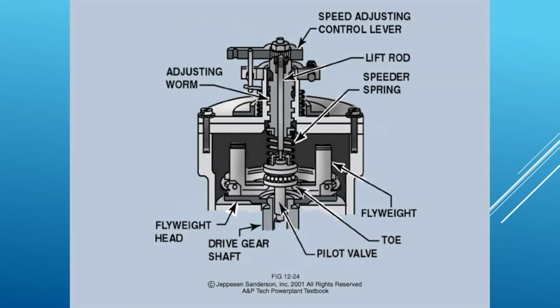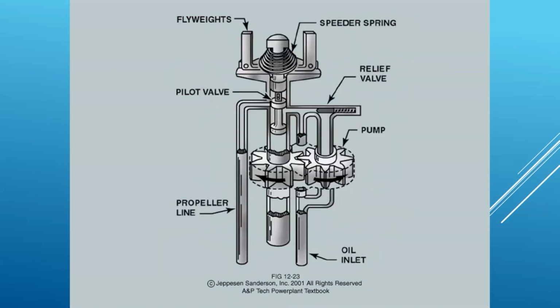To make it a little bit more complicated, we add a little bit on. So here's our same fly weights going to the pilot valve. Now, the opposite can be true as well, I should say. If this was lower, when the weights come in, this drops down, we can make it work the opposite direction. So this one just happens to increase blade angle as the speed increases, which is to slow the plane down. It sends pressure out.